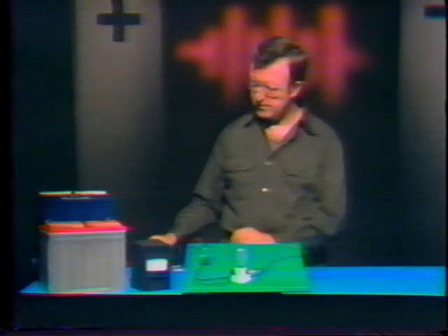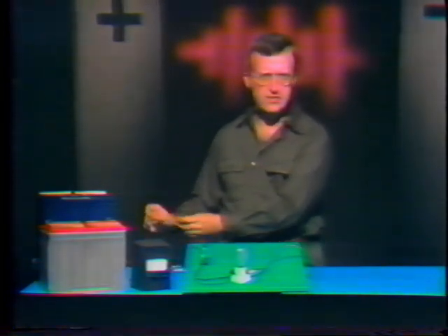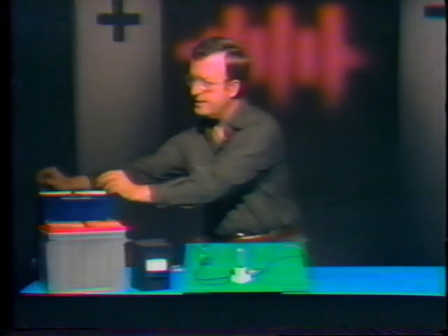I'll use a voltmeter to see just how much voltage it can put out. Most storage batteries have a discharge value of about 1.7 volts per cell. Now, if this battery is like most, then I should get a reading of a little more than 10 volts. 1.7 times the 6 cells in the battery comes out to just over 10. All right, positive to positive, negative to negative. The voltmeter shows a little more than 10 volts.